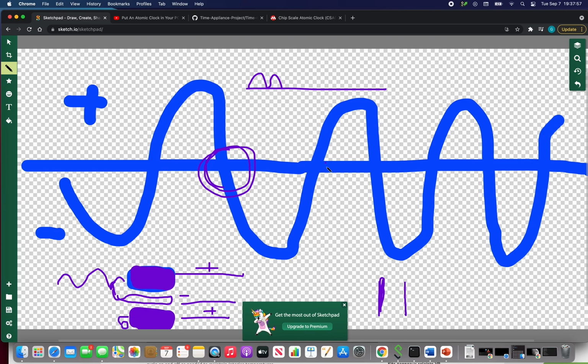You still have some difficulty in this region where it's about to change, and then you might need some diodes or something instead. But these diodes don't have to handle the current doing these big spikes here, or right here, where it's more regular. Just at the very intersection is where the diodes have to be. And you can use cheaper diodes that switch on, that are more conductive there, with less loss.